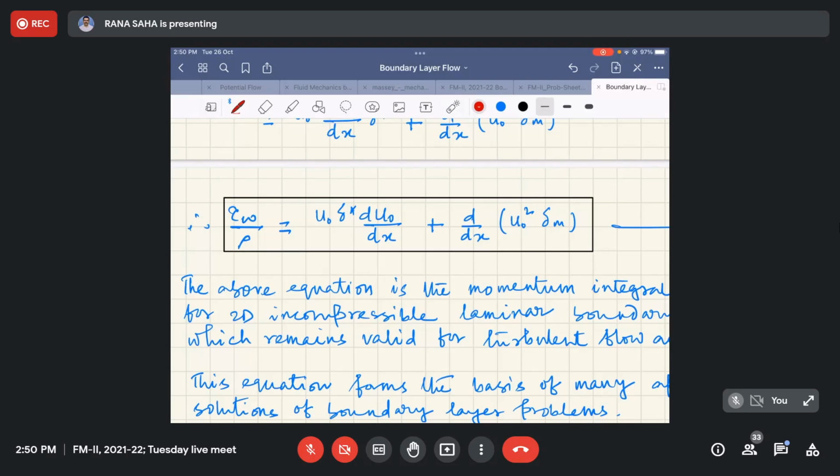section. So there, you see, your U naught, or in other words, the velocity at the center, which we can say as the maximum velocity. So that maximum velocity may not remain constant at different cross sections due to this convergence, or the other way if it is a diverging section. But we can say that center line velocity is out of the effect of boundary layer.